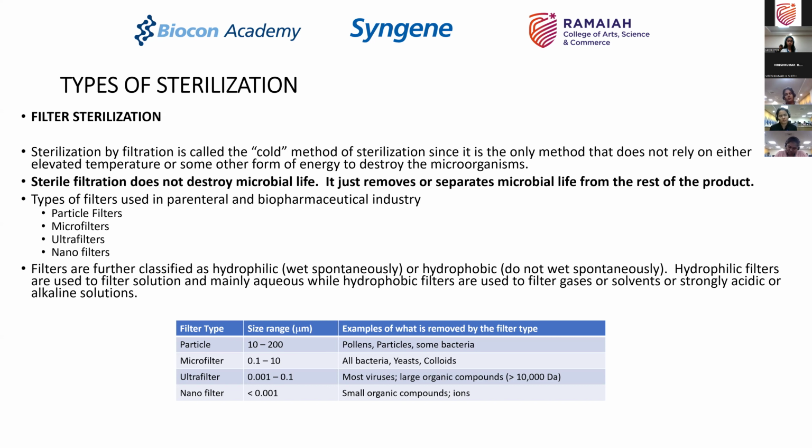Actually, if you look at filter sterilization, it is wrong to say that it destroys a microorganism, because filtration does not destroy the microorganism. What filtration does is, genuinely the word filtration, it filters out the microbial life from the rest of the product. By choosing the right kind of filter media, you are able to retain the microbial life on one side of the filter, while the rest of the liquid along with the product passes on the other side. Therefore, you are separating the microbial life from the rest of the product and not actually killing those microorganisms.